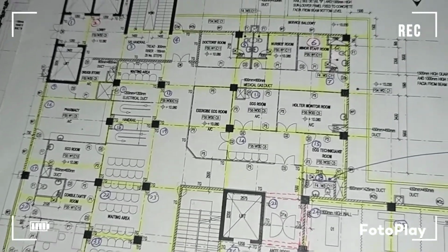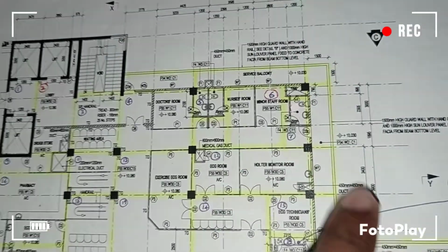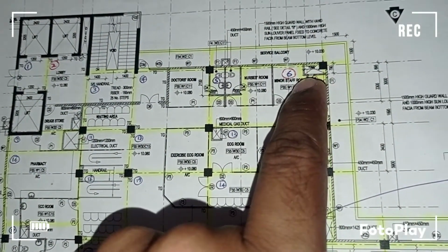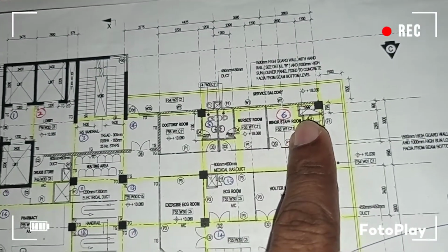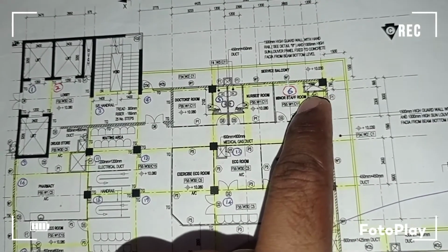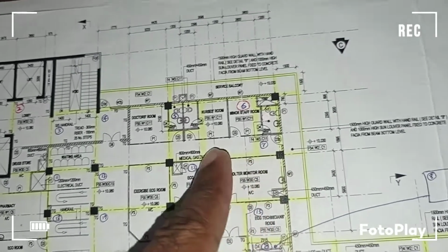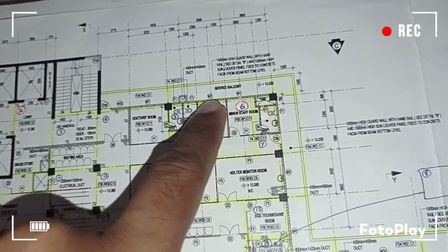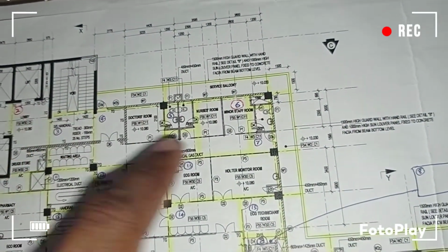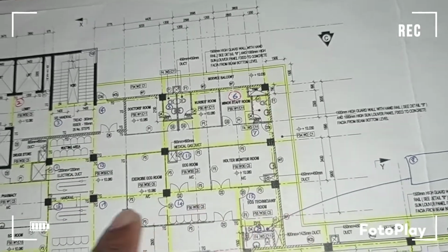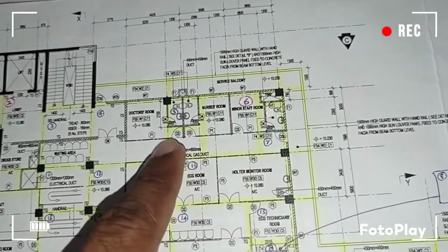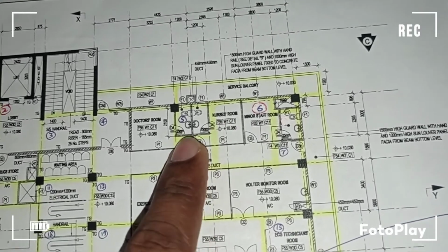When you see this panel here, you have some sort of large duct. For that you have to put a secondary beam here, another secondary beam here, and these are primary beams. Primary beams are going in the main grid lines. You can clearly see. And when you have a situation like this, you have a bathroom, washroom here.